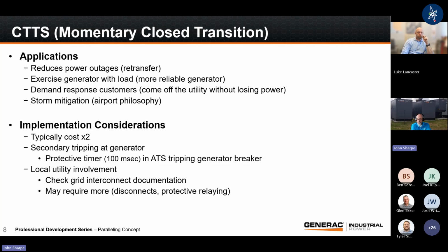Most standby generators, the generator exercises once a week, once a month. It's on Tuesday at 6 in the morning. No one really notices, right? It does its thing out of sight, out of mind. But when you're dealing with economic dispatch, that can happen in the middle of the day. You don't want to disturb the work that's going on within your building, either just the lights blinking or computers going or a manufacturing process where you may have to shut things down as we transition across. This way, we get a seamless transition between the two and don't notice anything.